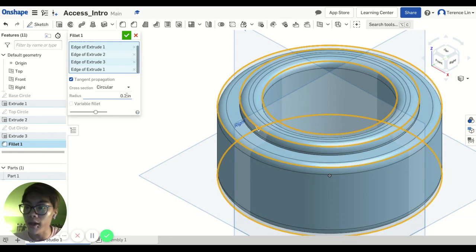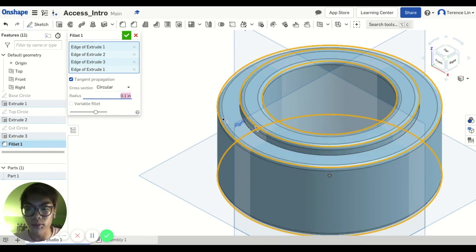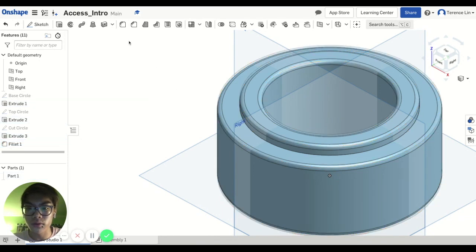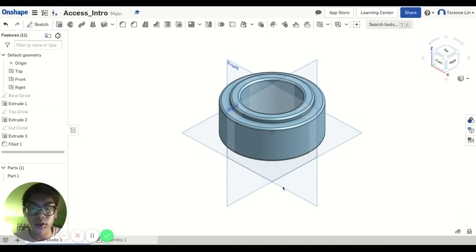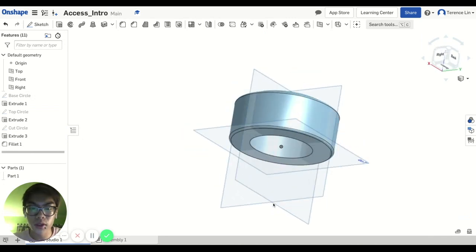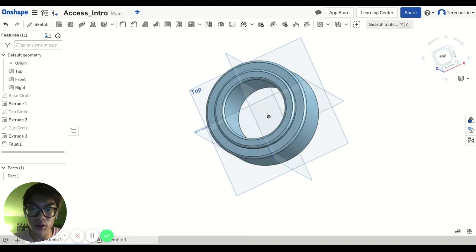And you can also choose the radius of how far you want this kind of smooth cut to go, because it's basically a circle at the end. If I want it big, I can go bigger, but I'm going to go a little bit smaller, so I'm going to go 0.1. Click enter, and you'll see it smooths out a little bit smaller now. I'm going to click the check mark. Done. Shift 7, and now you can see this kind of rim, wheel that you just made.